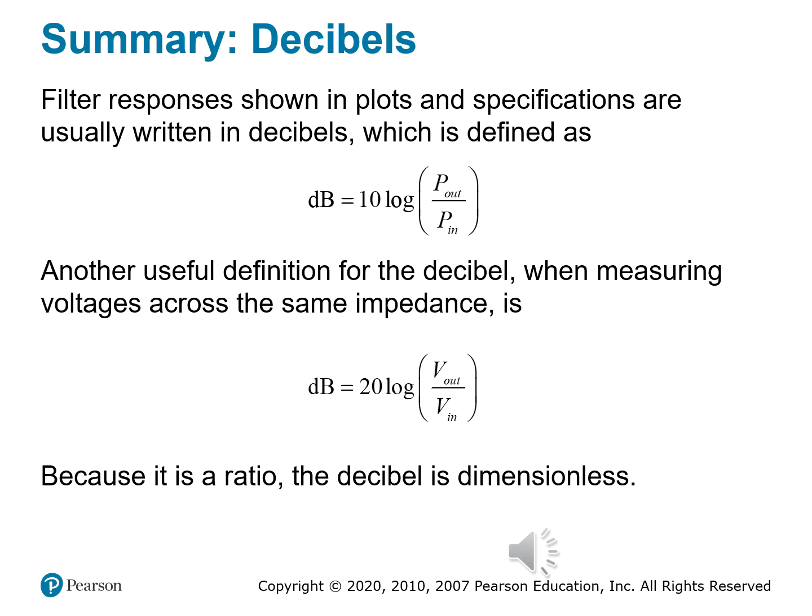It's a pure comparison. If we look at a 3 dB drop, that just means that your voltage has fallen, sorry, to 70.7% of that starting value. So is any of this sounding familiar? Hopefully it is. And that's our critical frequency from earlier. So next time you're reading a filter spec sheet or plotting frequency responses, you know exactly what those dB markings mean. So stick around. We got high pass filters coming up next.